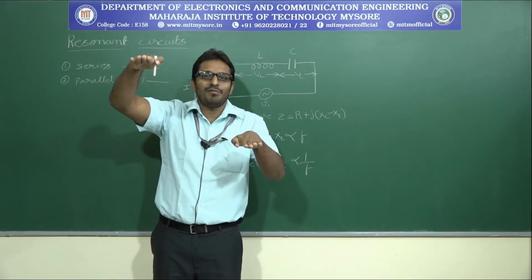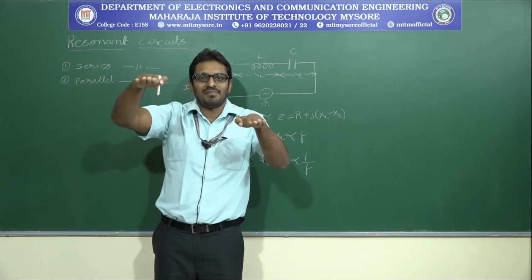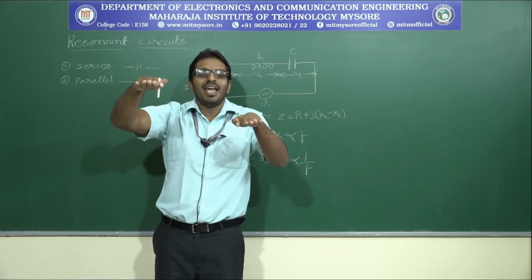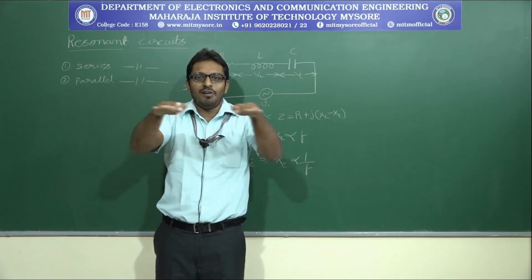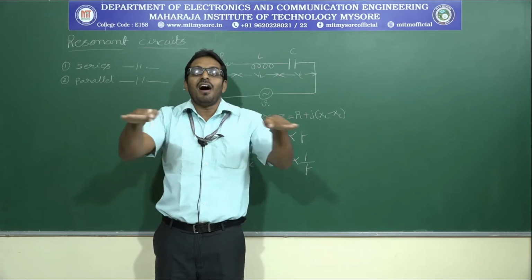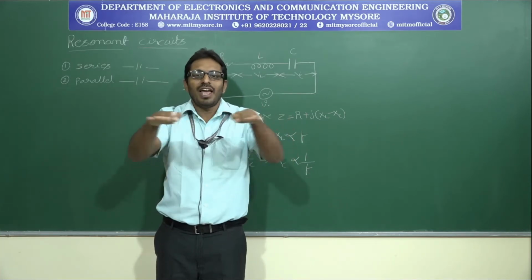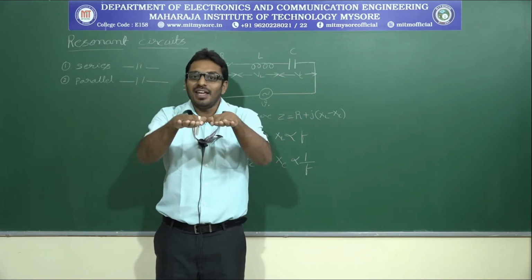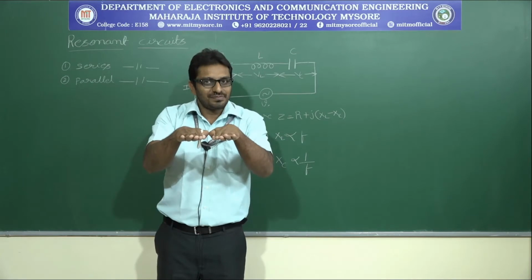Again, further increase the frequency, XL increases, XC decreases. At a particular value of frequency, both XL and XC are equal. That is known as resonant condition.